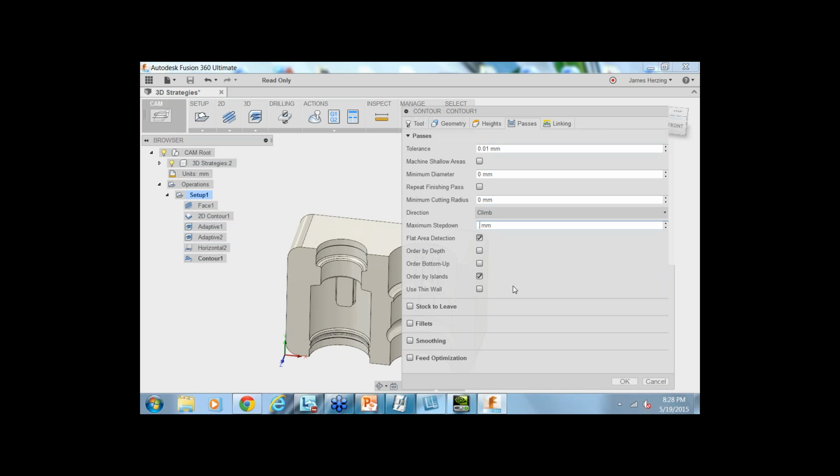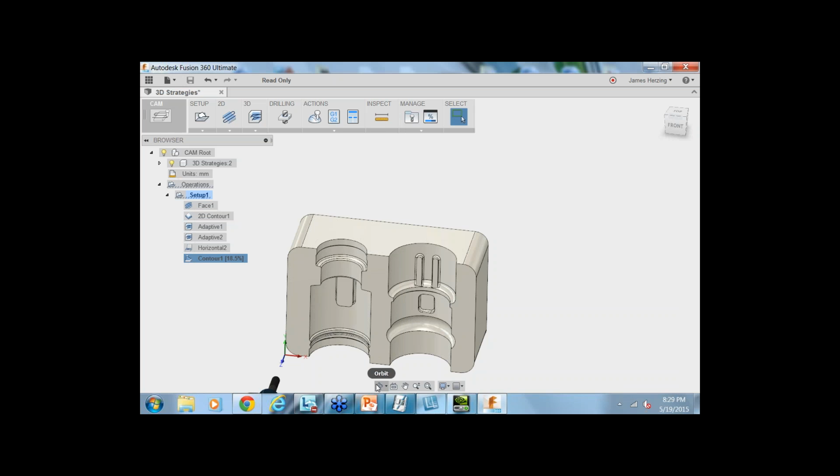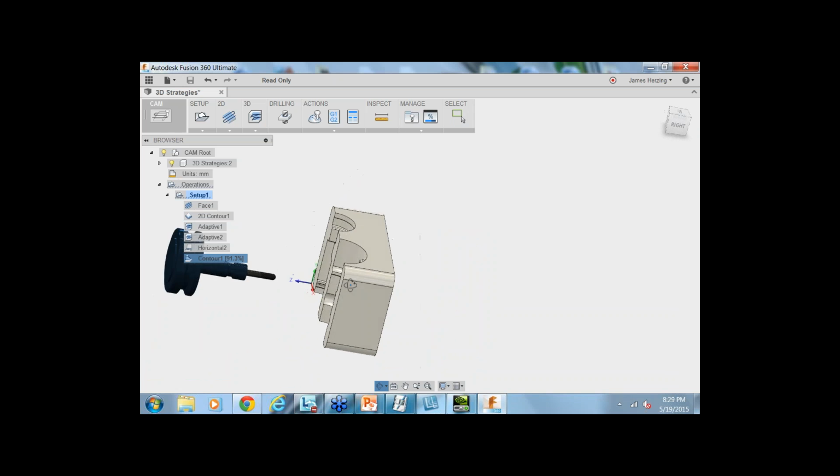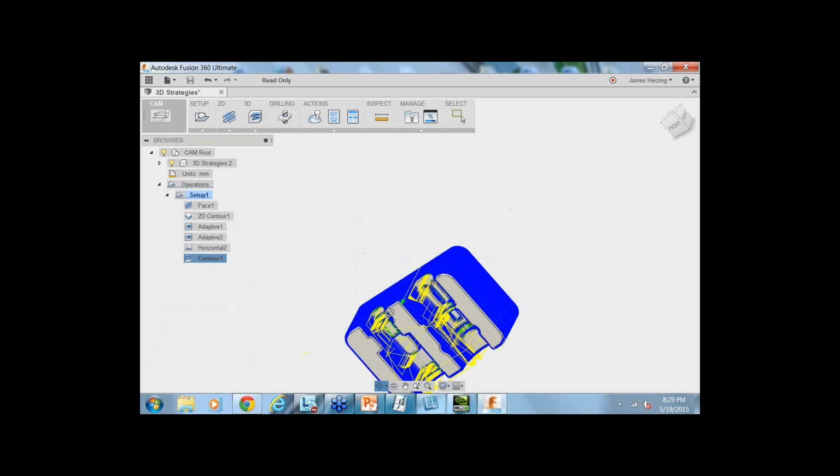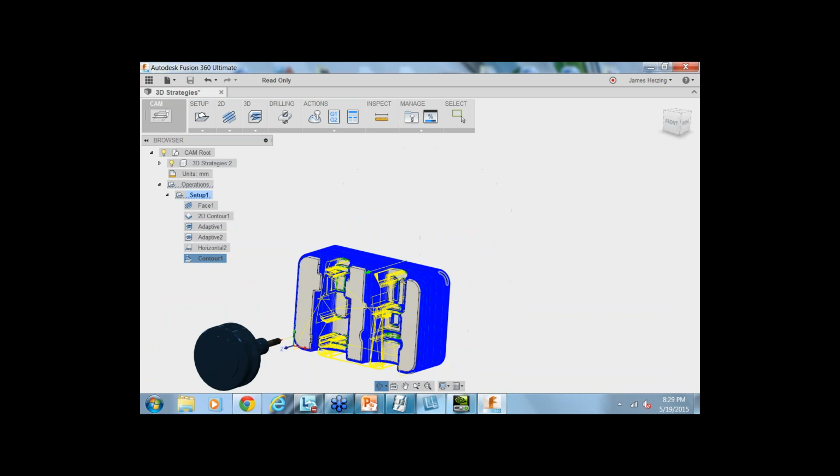Is 30 reasonable? 30 degrees? I mean, is there a limit? Clearly there's a limit, but what is said limit? Typically you'd want to watch out for head crash, so it depends on the profile you're machining. If you have something with a very sharp angle, you're going to have fewer degrees than something that's much flatter and more open, but you don't need slope if you have a flat, more open part. So typically it would probably be about 45 degrees. Okay.